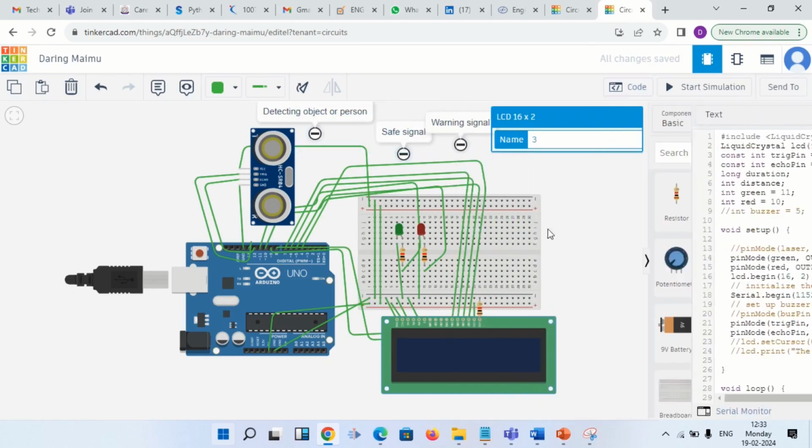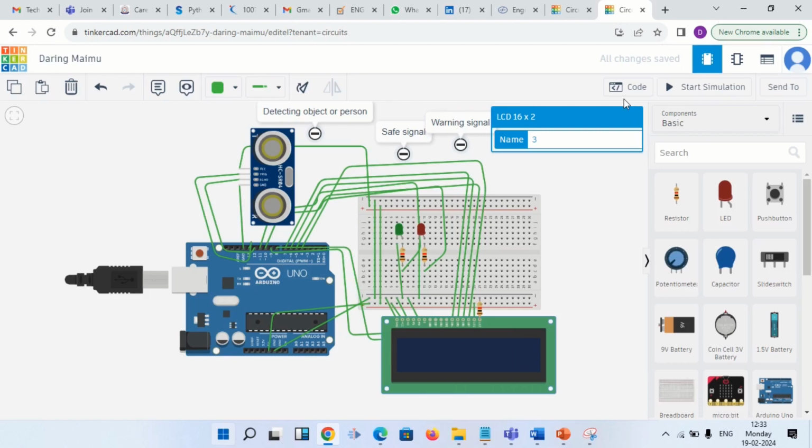Some logic high, logic 0 pin we have to connect, and 6 pins. Here 4 pins, and in this set two pins. In total, 6 pins you have to connect with the digital pins of the Arduino. If you want to know the connection, you can get it from the internet. The respective code for the LCD you can also get from the internet.